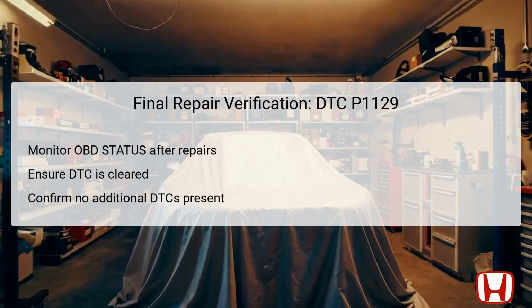Final repair verification is critical to ensure that the repairs made during the troubleshooting process have resolved the issue with the MAP sensor. After completing all necessary repairs, monitor the onboard diagnostics (OBD) status to confirm that the DTC P1129 is cleared.